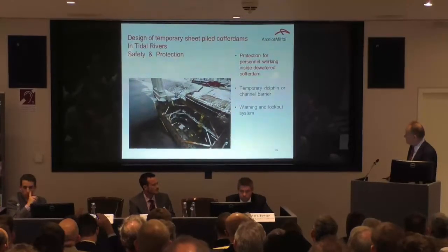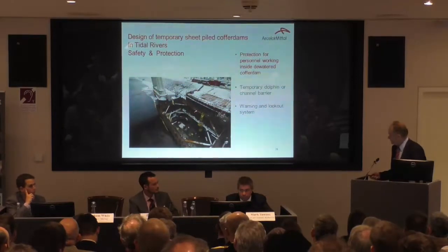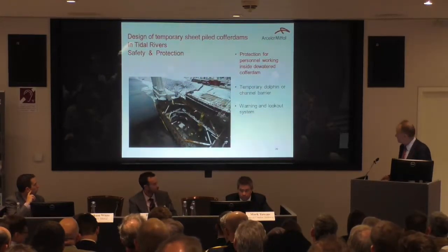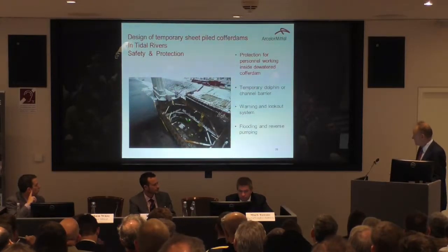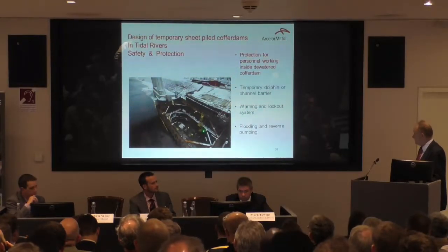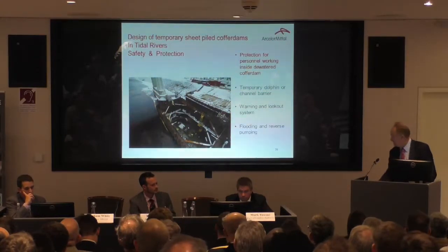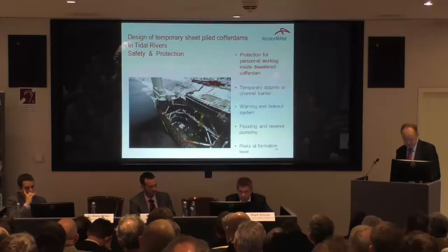So it's best in the temporary phase to have a warning system or a lookout or some means of making sure that there's no impact in this very vulnerable stage of the construction of the cofferdam. Flooding and reverse technique to make sure that the base is constructed safely before there's any risk of anything going wrong, especially by having something hit the outside face.